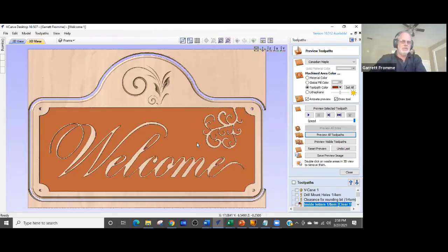Ideally, we like to avoid doing that, but that's part of CNC work. Sometimes we just have to do that. What I find a lot with CNC is people don't like the idea of running their machine more than they have to. Some people want to get everything done in one pass instead of running a finish pass. But in my CNC work through all my years, a finish pass is just a gimme as part of the process. So don't be afraid to do a finish pass if you want to get better results out of your machine.